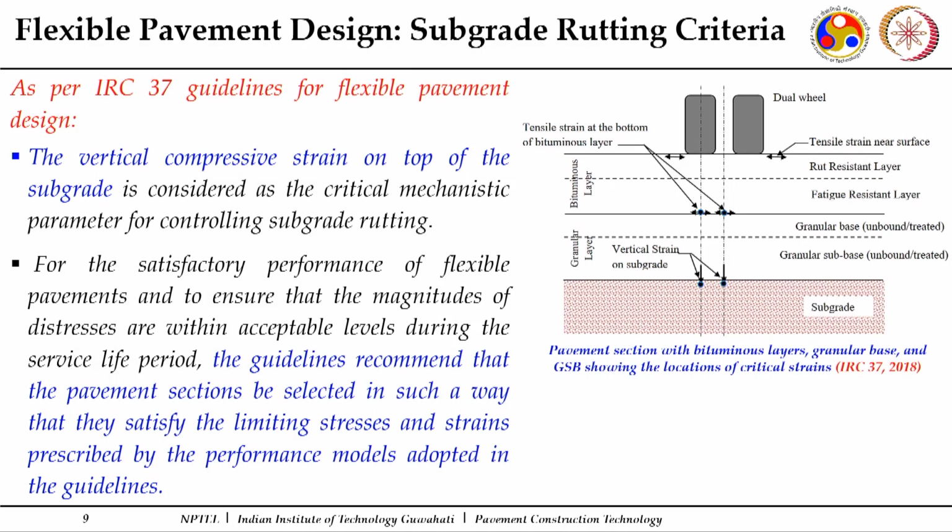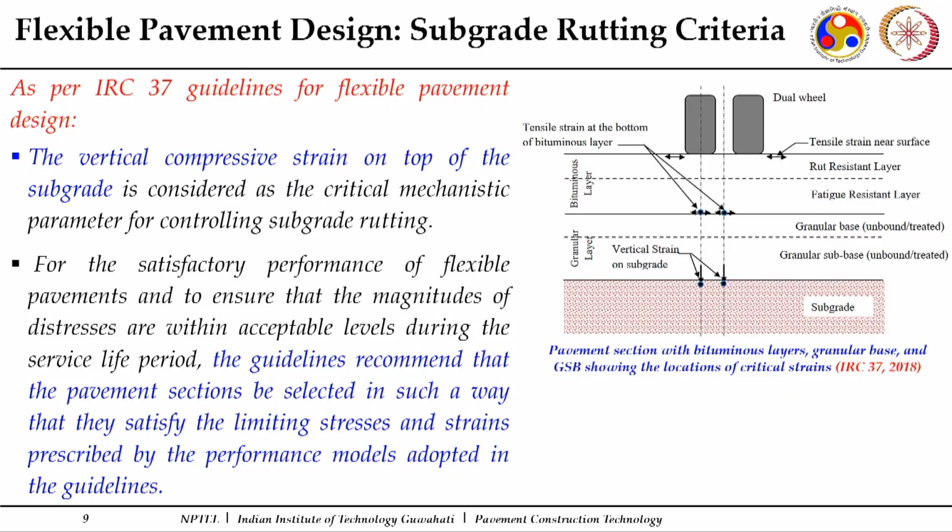Now, this is the concept behind the flexible pavement design. The approach we follow is a mechanistic-empirical approach. Whatever layers we construct, we consider them as an elastic layer system. So, we have a subgrade, which is a semi-infinite layer. We have the layers, which I can divide into two major groups. One can be my granular layers, the second can be my bounded layers, the bituminous layers.